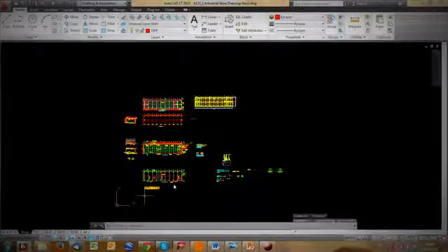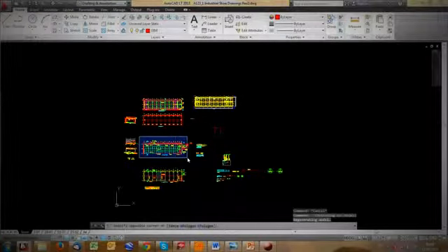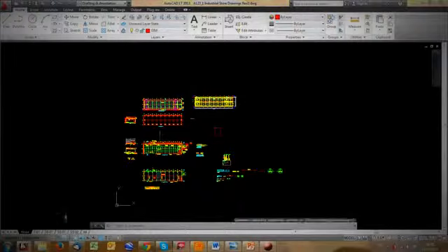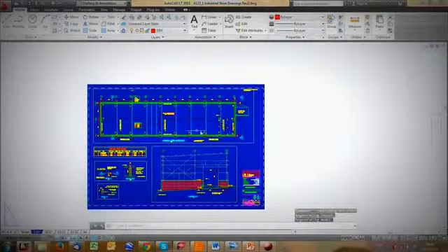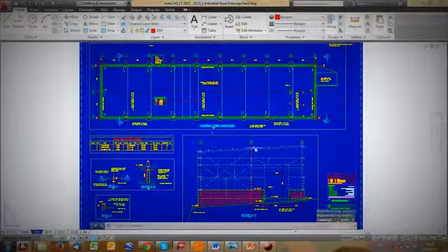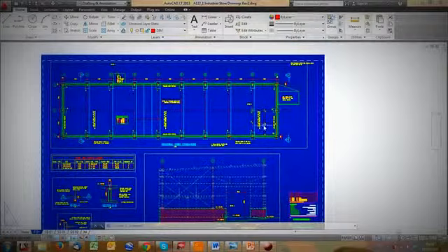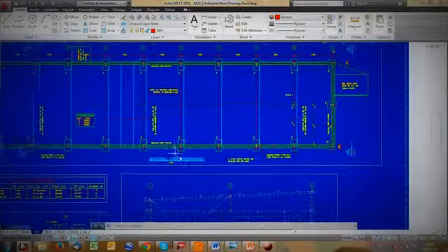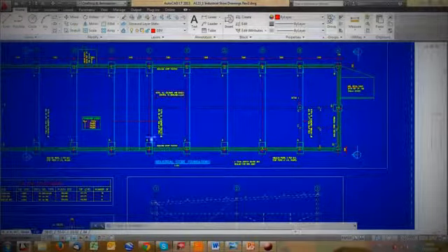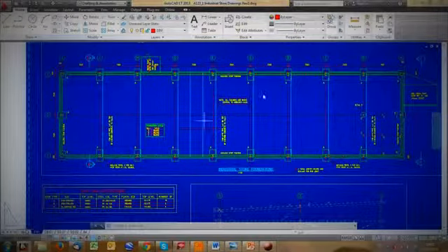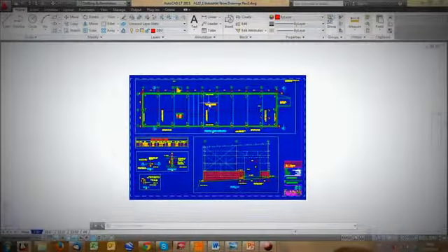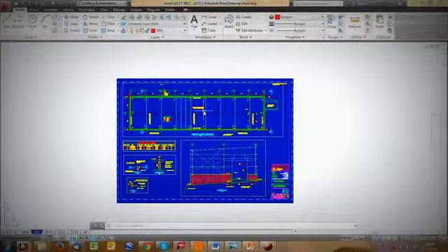So from model, you set up a window around. So I will see what's in that box right now. But you create those windows from paper space. So if you go into paper space, you look now through these windows. And what you must be careful of is even though you draw at 1 to 1 in model space, all your dimensions, your stars, etc. must match the scale you use in paper space.